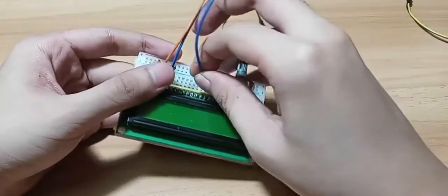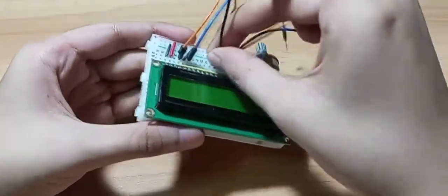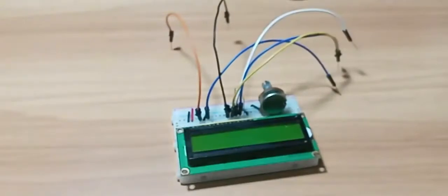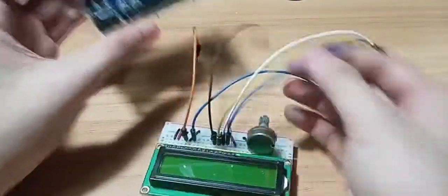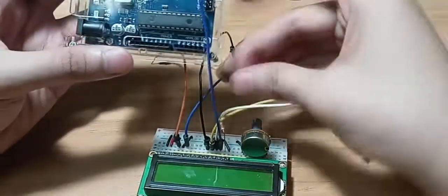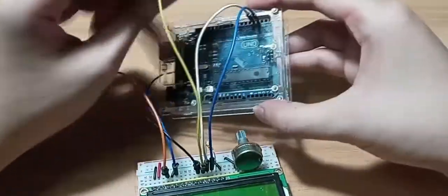It is essential to use the #include LiquidCrystal when using the LCD display. With this, we can actually use the LiquidCrystal functions. There are 19 different functions in the LiquidCrystal library available to use. These functions do things like change the position of the text, move text across the screen, or make the display turn on and off.